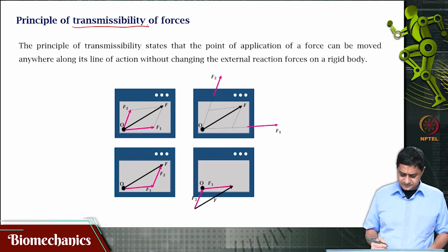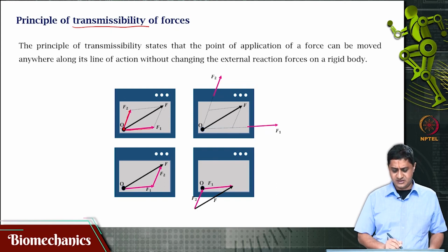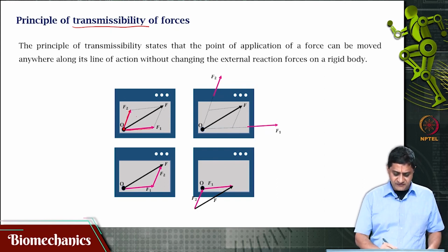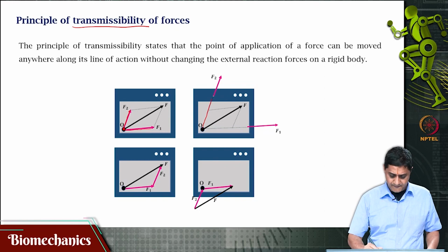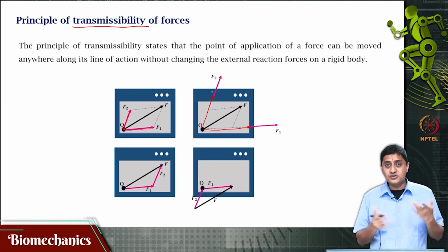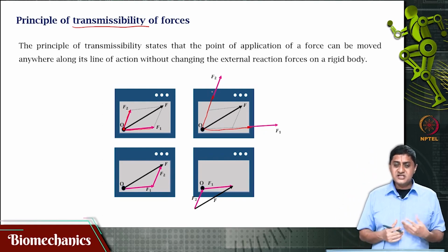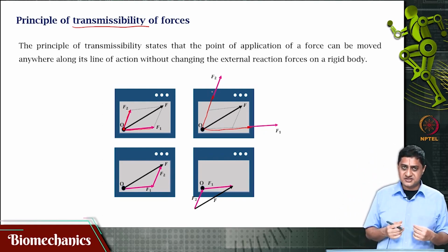Let us say in this case force F1 and force F2 are acting at this point O. Now I know that the line of action of this force is along this line, right? Now I can move this F1 to act from this point and F2 to act from this point without changing the analysis. This principle is called the principle of transmissibility of forces.